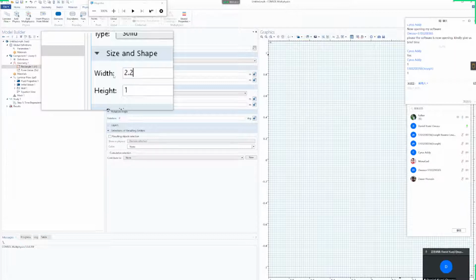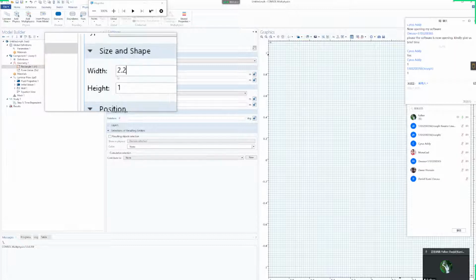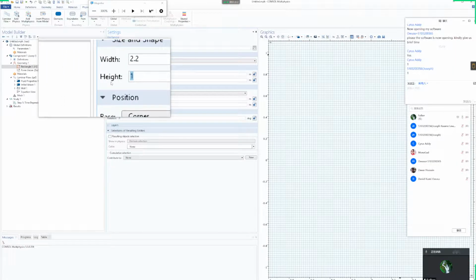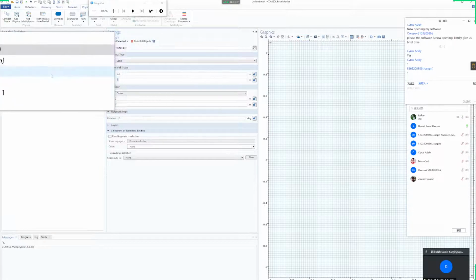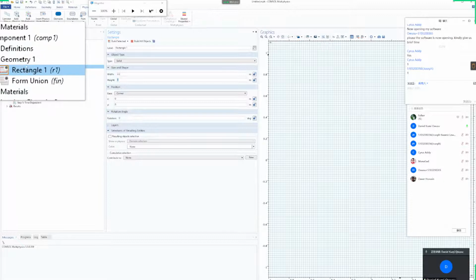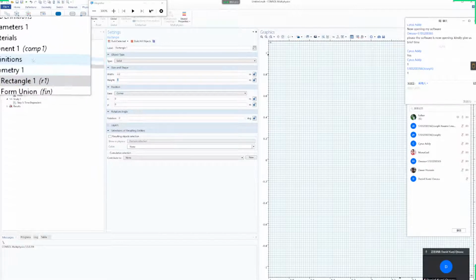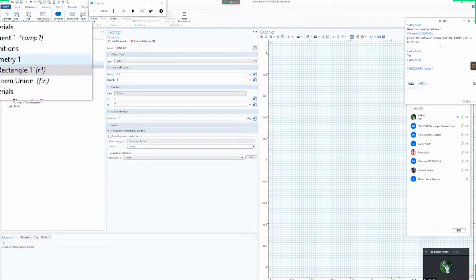Excuse me, Prof. What's your question? Please, yes, please. After adding, selecting the laminar flow and adding, can we start from that side, please? You will come to a study. You should add a time-dependent study. Okay? Just double-click it.